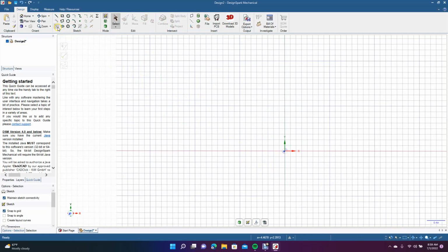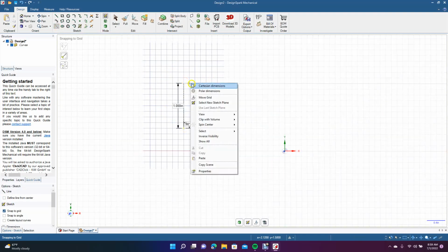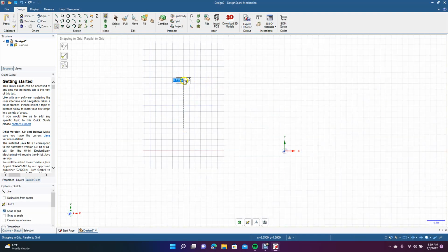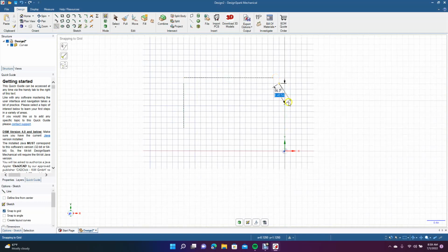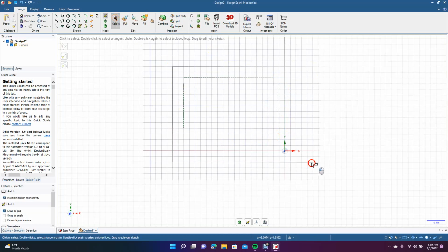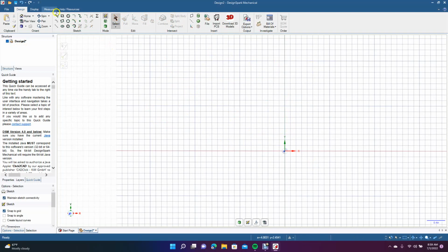This is going to be your construction line tool. This is pretty handy to have if you want to create lines, but you don't want to create permanent geometry. If you wanted to set up a mirror line, you could use your construction line.